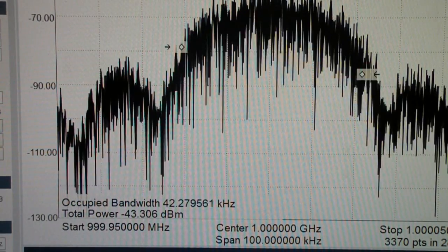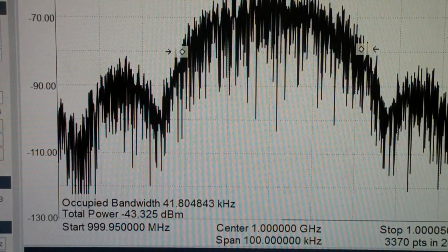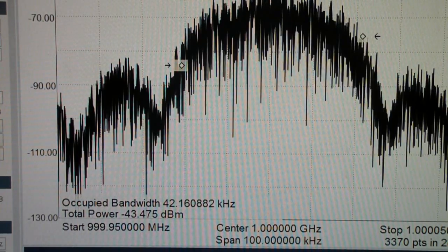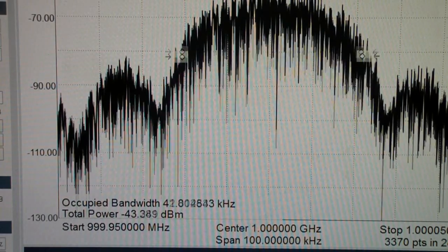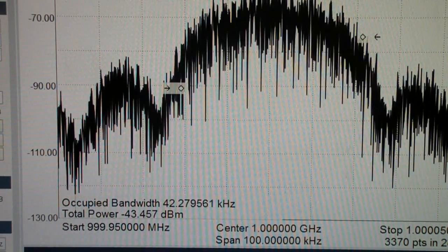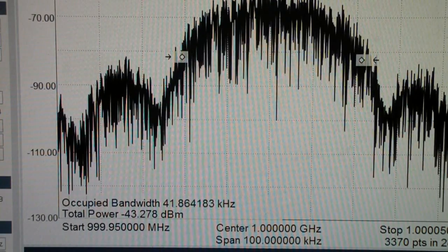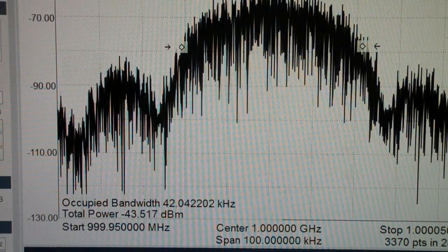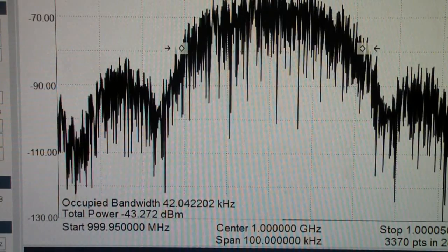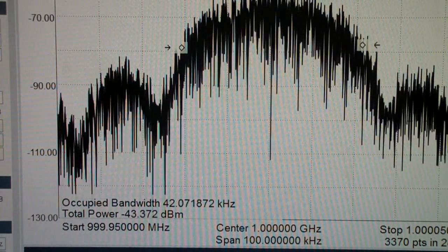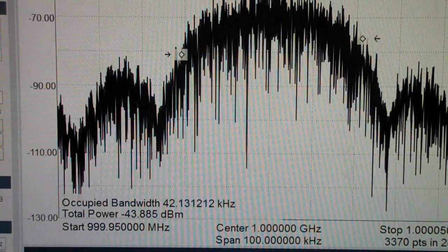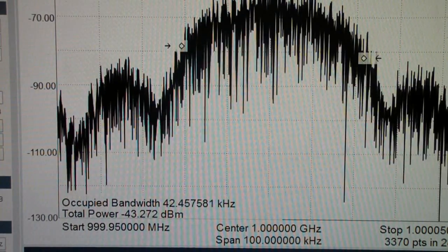The lesson here is that by proper filtering in the baseband, by using a Gaussian MSK signal, you can do frequency shift keying in ways that not only lower the occupied bandwidth, but also reduce the inter-symbol interference, as well as reduce the error rate by causing the frequency changes to be phase coherent.